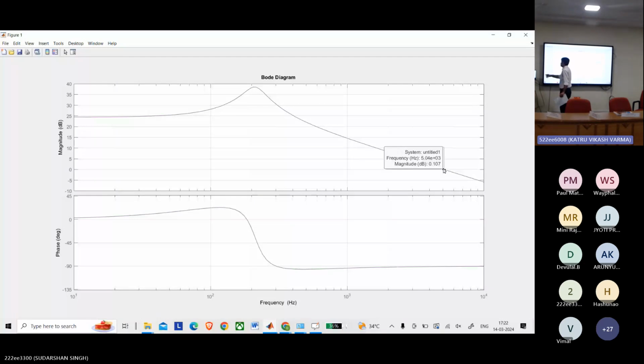Okay, so you can use the stability tool. You can get all the stability margins. So you can see that the uncompensated system has a phase margin, because it's 90, and minus 180 is your reference line. So there is almost 90 degrees of phase margin, and the uncompensated system bandwidth is approximately 5 kilohertz. And we want to design the PI controller.